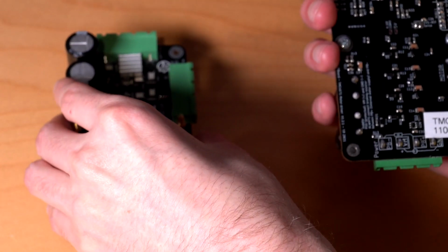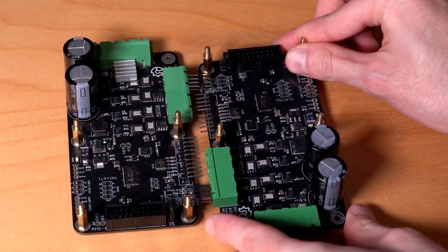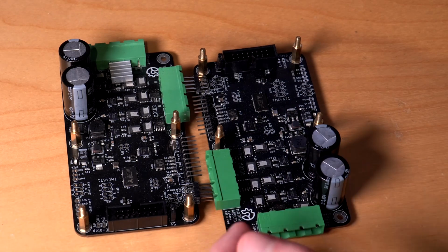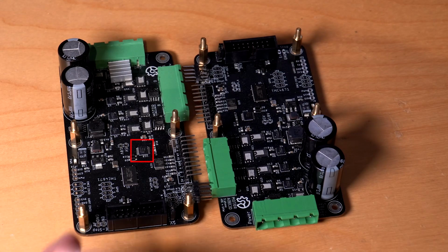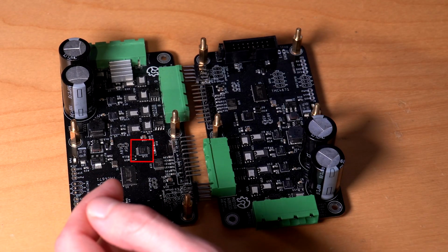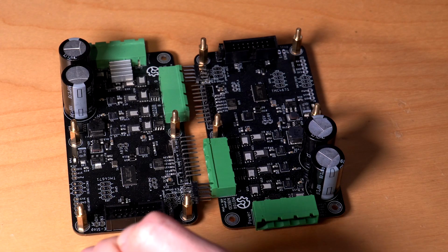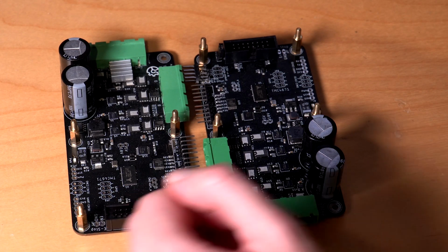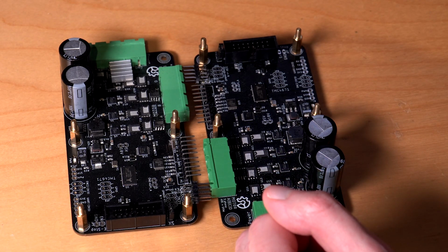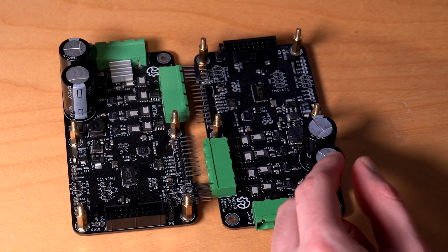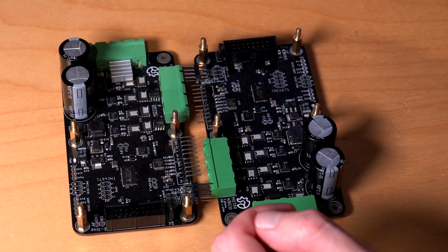Also, as mentioned previously, the ADC inputs of the TMC do leak some current out and require a buffer driving them. So a quad op amp was added to the design as well, which is used for the temperature sensor and the voltage divider, making them more accurate. The third channel buffers the 2.5 volt reference, and the last channel was used as a comparator to activate the brake resistor at a fixed point if the software activation fails for additional redundancy.